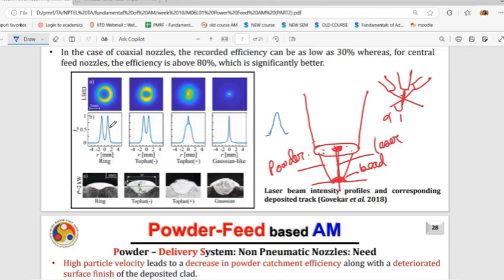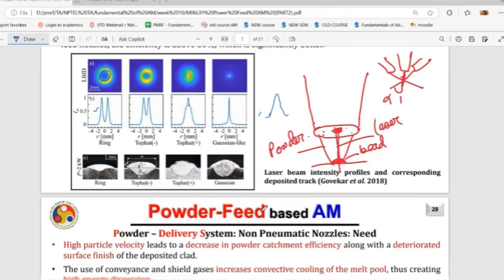use for DED. And let me tell you one thing. It's proven by literature that when you use this type of peak, your deposition rate increases because you actually entrap the whole powder inside this zone. And at the edge, your laser is coming, so your deposition rate increases rather than with the Gaussian wave. So these are a few studies people are doing so that you can optimize the deposition rate first, which is the main problem in DED.